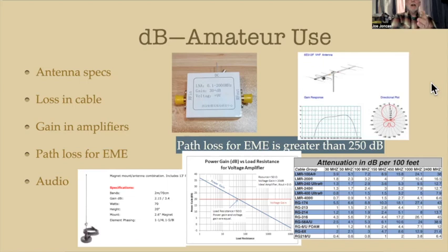Yeah, say you've got an antenna and you're pumping 50 watts into it from your VHF transceiver. And if it's just a standard vertical with a ground plane, that would be the gain of a dipole. If you got a Yagi and it had a 3 dB gain over that dipole, that would be double. So you go from 50 to 100 watts, which then again, 3 more dB would make it 200 watts.